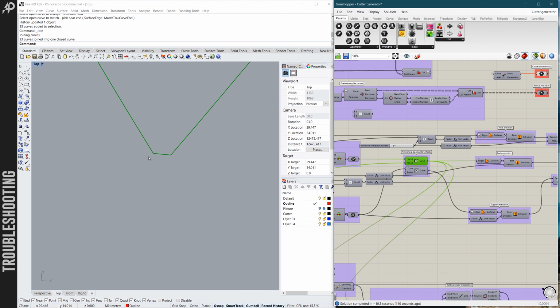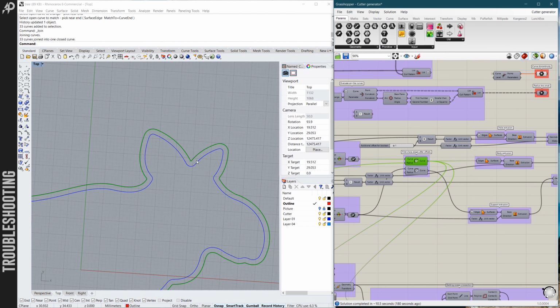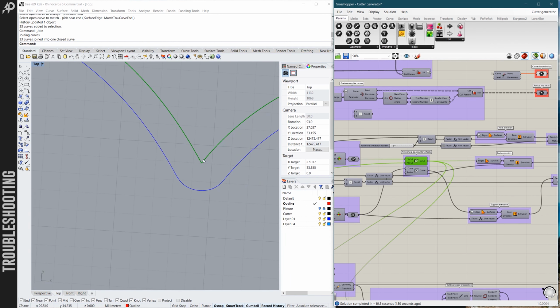And now we see the problem. We got into a very awkward situation where offset caused that there is no sharp corner here, or to be more precise, there are 2 sharp corners, and Rhino attempts to create 2 fillets, but there is not enough space for them. If there only was 1 sharp corner, there would be no problem creating fillet, but since there are 2 very, very close to each other, fillet just doesn't create. And now at this point there is no other solution than to recreate our initial curve.